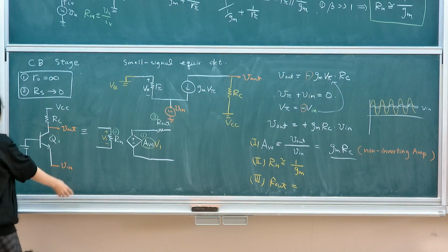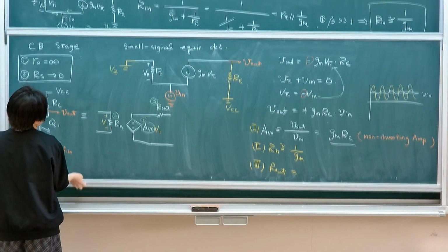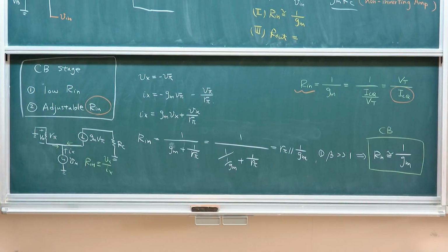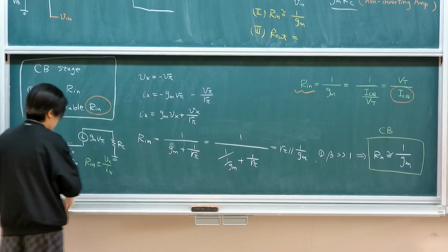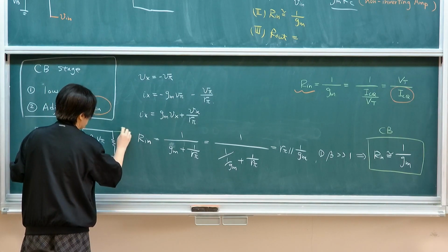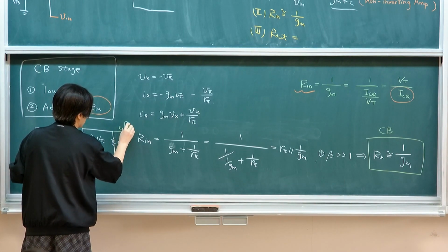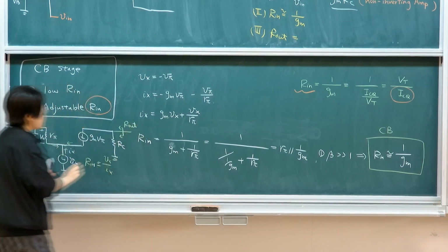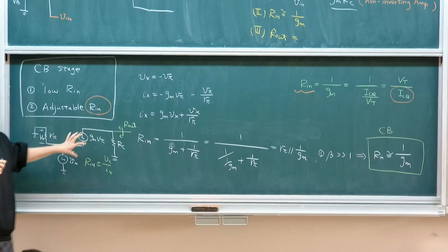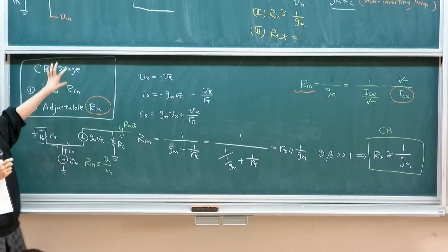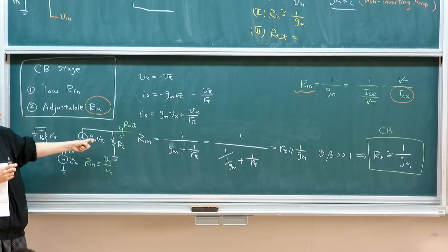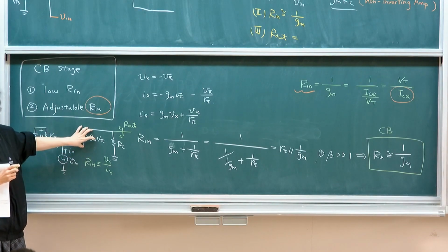So going back to this equivalent circuit, you could actually get the output resistance fairly quickly. If I'm looking in from here, if you ignore the effect of output resistance, RO, of the transistor, early effect, this will then give me infinite resistance.